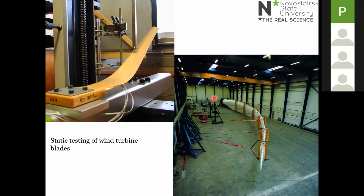When blades are made, blades of all sizes go through a static test. And this static test, where you simply pull the blade away from its mounting, you can see at the back here, or more clearly here for this smaller blade, gives you measurements of the deflection of the blade. And that is very useful information from the structural perspective, because you can compare those measurements to the prediction of usually a finite element structural model for the blade. And that's a really important part of ensuring that a wind turbine blade is safe.